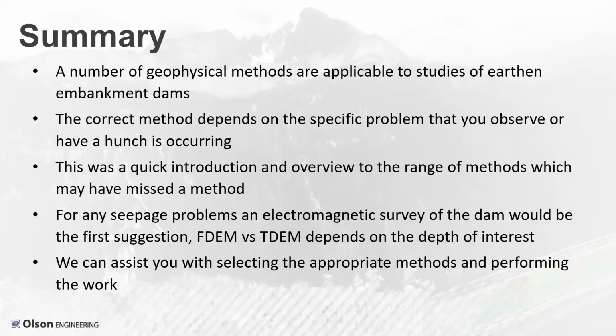All right, so to summarize this presentation, there are a number of geophysical methods that are applicable to studies of earthen embankment dams. Which method you select depends on the type of failure mechanism that you're worried about. If you are worried about seepage issues, then you're probably going to pick an electrical or an electromagnetic method.